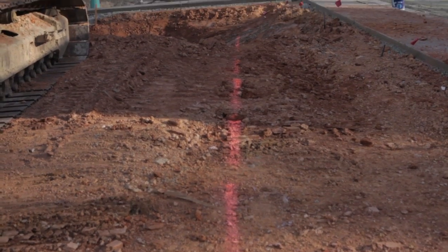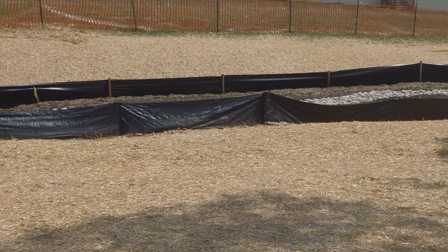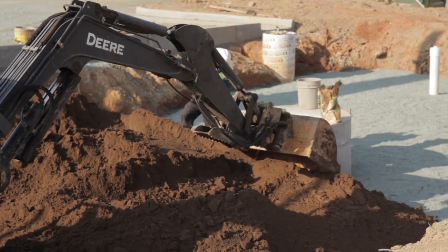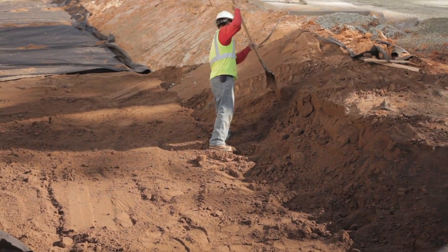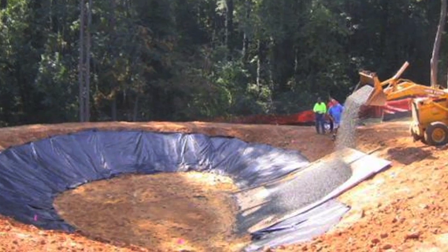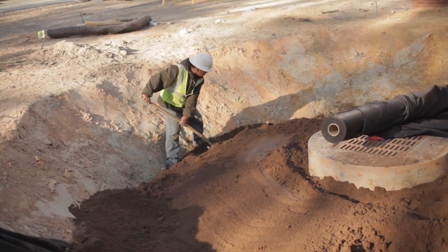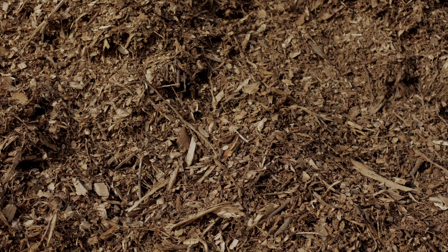Here is a typical construction sequence for building stormwater BMPs. Start by locating and marking underground utilities. Next, stabilize the drainage area. Then, install sediment and erosion control measures. Properly select and use equipment for excavation. Next, ensure the base and the slopes are as designed. Ensure the materials meet the specifications in the design. Properly use filter fabric. Install underdrains and cleanout. Compact the site properly. Ensure elevations are correct. And finally, install vegetation and mulch.